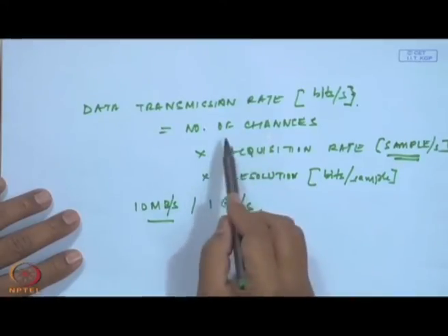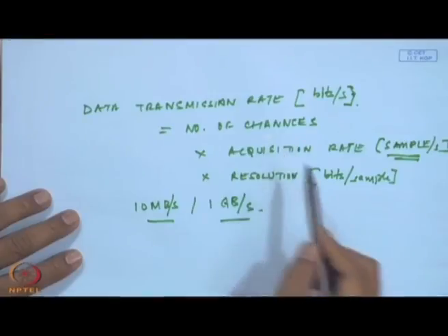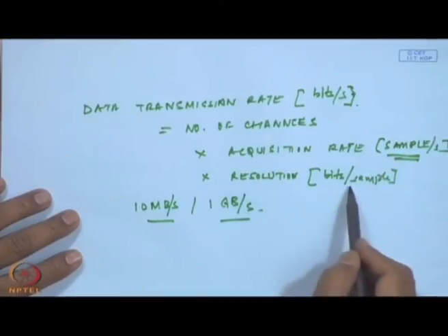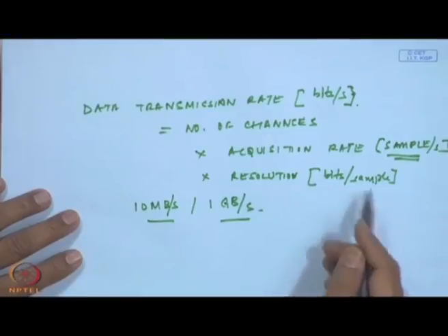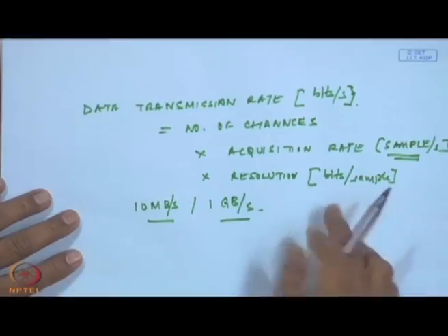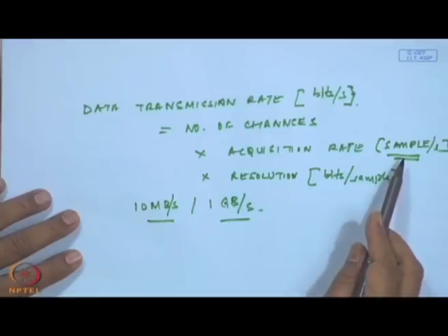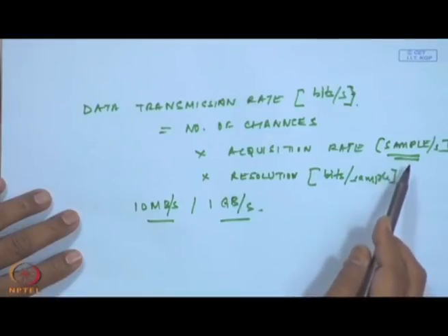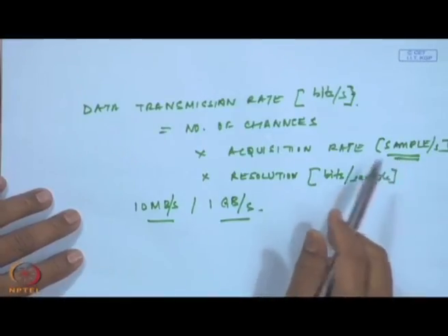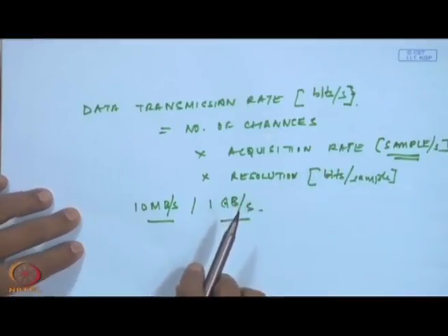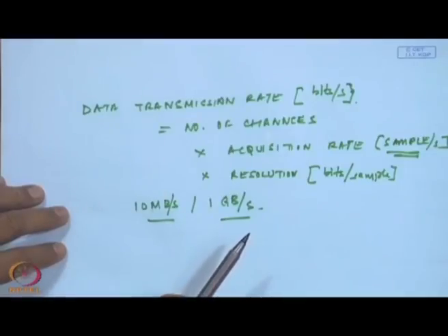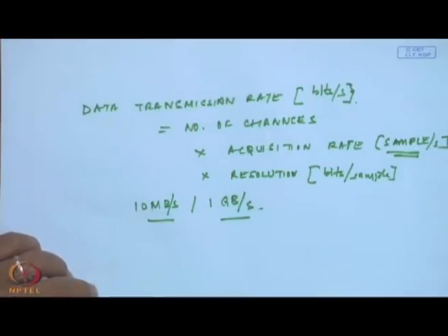This depends on the number of channels of data you are transferring, the acquisition rate, and the resolution. Typically, the resolution people use nowadays is about 16 bits or 24 bits, and for a low frequency signal it is easier to transfer by wireless. But when we are talking about high frequency signals, where you want to send 10 channels of vibration data over wireless, the data transmission rate of present wireless technology limits this level of data transfer.